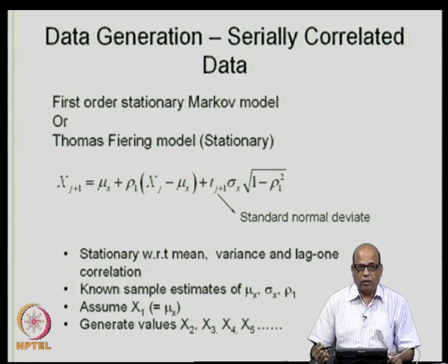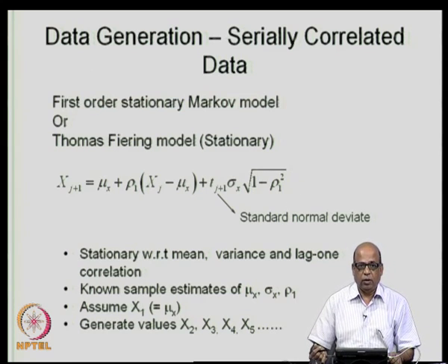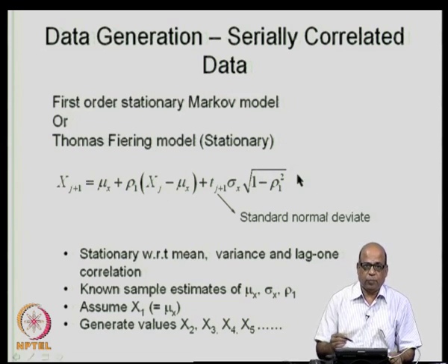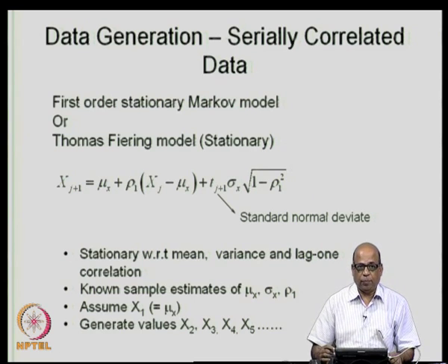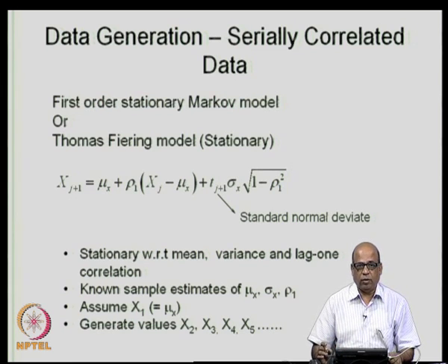If there are certain cases where the model does not perform well, either in terms of the standard deviation or in terms of lag 1 correlation, it then means that the assumptions that we have made in building this model, namely that it is a stationary model and that the flows follow a normal distribution, may not be valid for the data that you are using. So, a test for the model to be valid is that all the three, namely the mean, the standard deviation and the lag 1 correlation, must compare well between the historical data and the generated data.